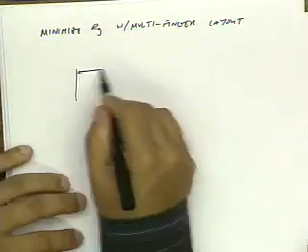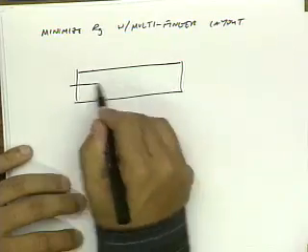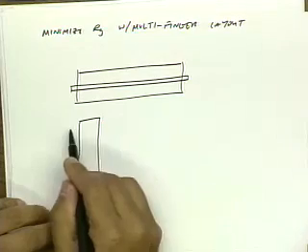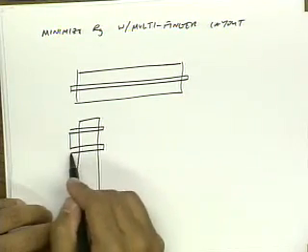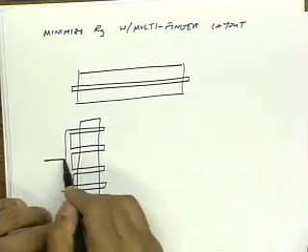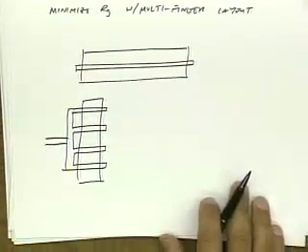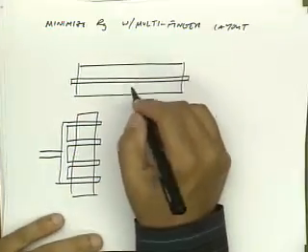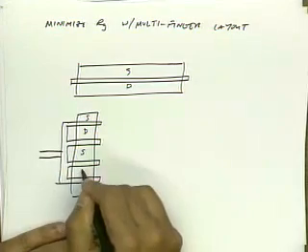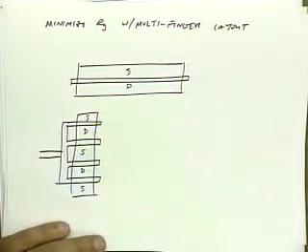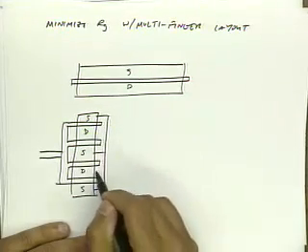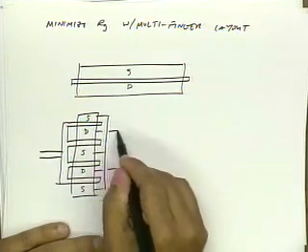In other words, instead of doing a device like this, I can lay out my device like this. And this is a standard trick in IC layout that you probably are familiar with. So here, if I have source and drain, over here I'm going to have source, drain, source, drain, source. And so I need to connect my sources together with some interconnect, and likewise my drain together.